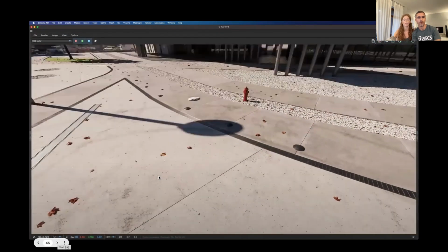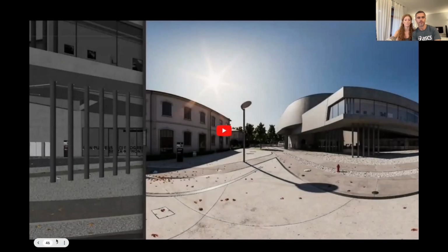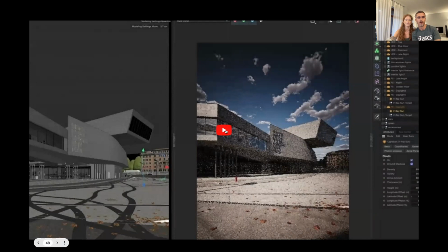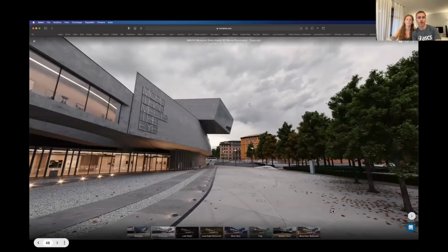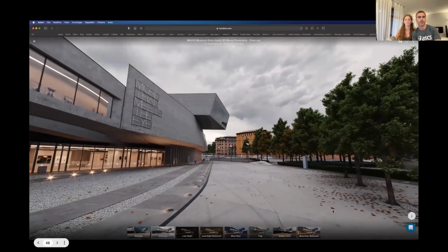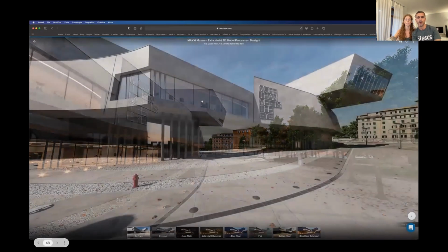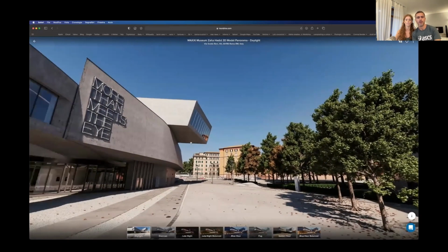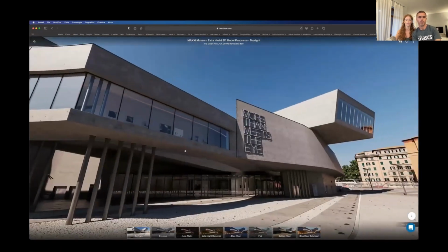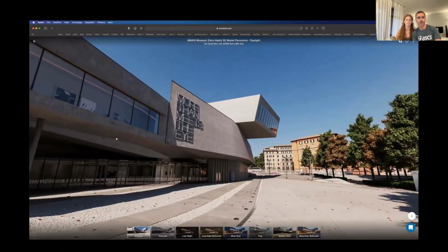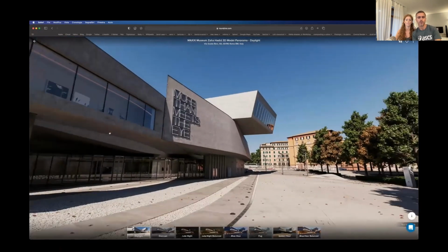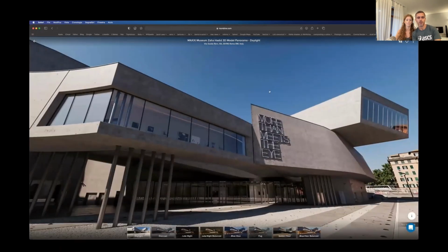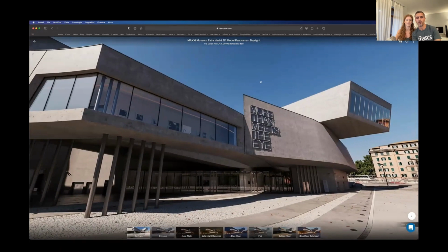Let's move on to the clouds. HDRs are a nice way to add clouds in our scenes, but to be honest, most of the time I end up using just standard physical sun and sky, because in the end it is much more flexible and the results are still great. That being said, clients may want a few clouds here and there from time to time. And now you can do that using the new cloud option inside the V-Ray Sun tab.